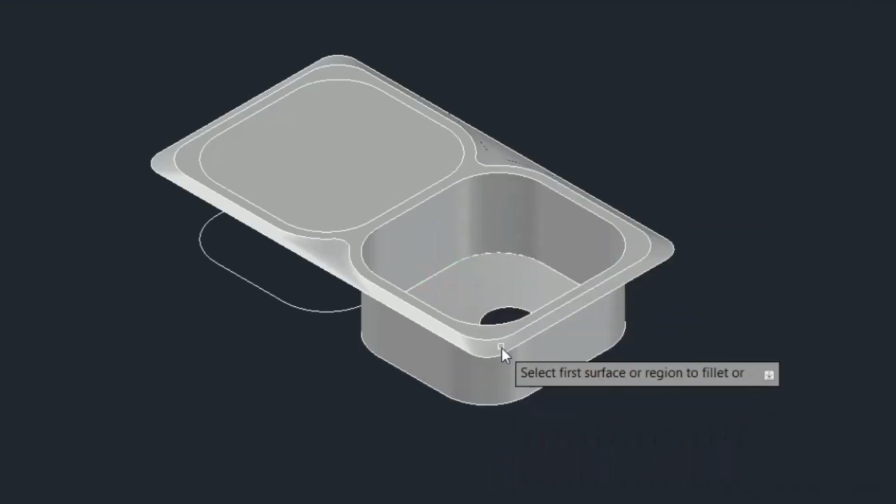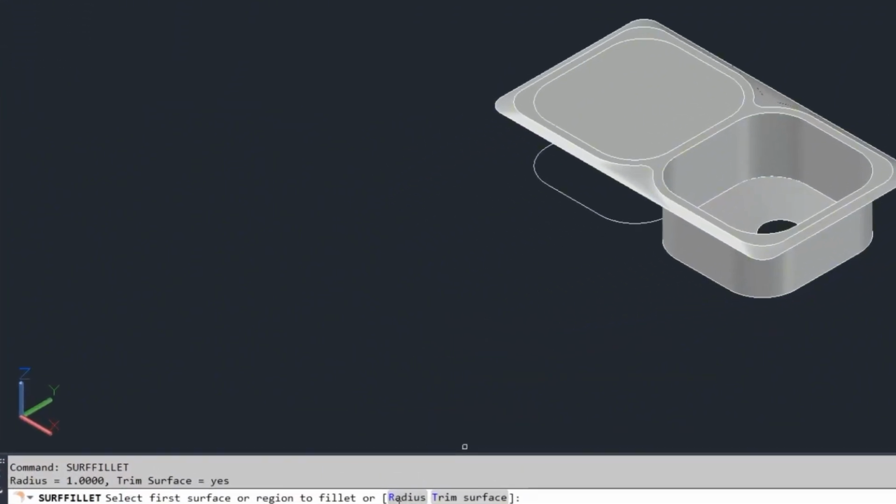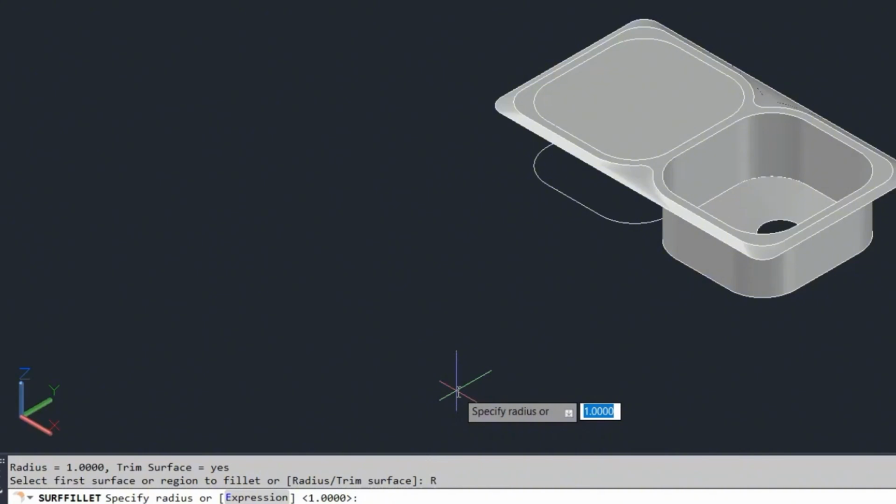So now you pick it. Then it asks you, look at the system. It says, is it trim or is it radius or trim surface? So you pick radius, and picking radius means you pick the first letter, which is R, to say that is what you're asking of. It now asks you, what are we working on? You now tell it, we're working on 15, sorry, not 12, 15. So we pick 15. Let's continue. And we press enter.